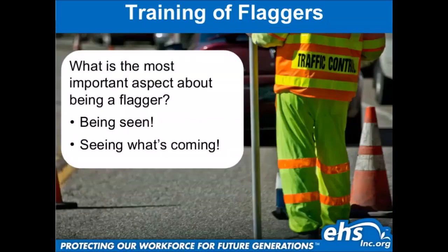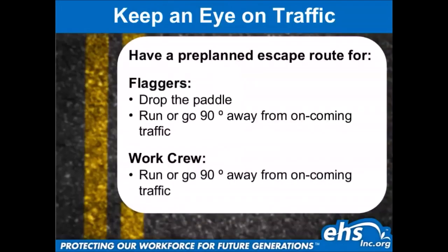All right, so in order to be safe as a flagger, guys, you have to be seen. You have to pay attention to what's coming towards you. There's a lot of accidents that happen where flaggers are struck because they take their eye off traffic, or they're paying attention to what the guys are doing instead of what's coming towards them. You guys know that not everybody stops for the flagger. If you ever get any of those warning signs, the red flags, that gut feeling that this guy is not going to do what he's supposed to do, then you're supposed to avoid that vehicle, right?